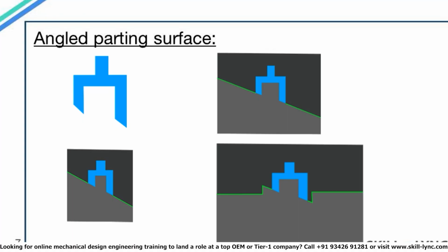the same angled surface. Even if you have the complete mold block at some angle, or if you have the mold block at some angle close to the component and then a flat profile, the end result as far as the molding of the component is concerned will still be the same. This addition of flat surface instead of angled surface is done only to allow easier machining.